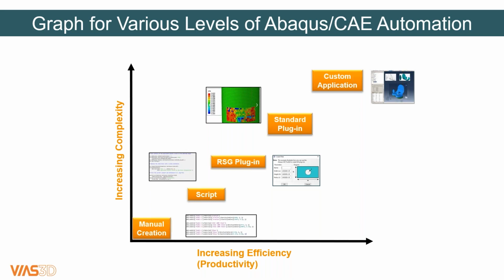In this situation, this is where you really change the look and feel of Abaqus. If you had a process you wanted to define and really strip out certain features, there are certain things you can't change. You can't just change the whole look of Abaqus, but you can make a lot of changes to file menus, toolbars, change modules, add modules. So you can really create a customized application that's tailored to your needs.